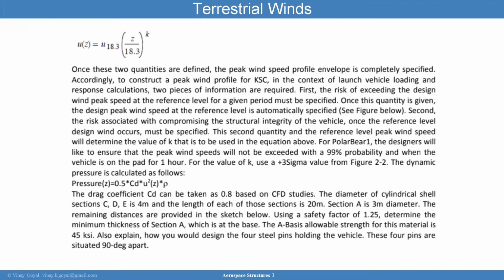Accordingly, you want to construct the peak wind profile for KSC in the context of the launch vehicle loading and response calculations. And you do need two pieces of information that are quite important. First, you want to know the risk of exceeding the design wind peak speed at that reference level for a period of time. So the longer you're on the launch pad, the more likely you are to exceed the design wind peak speed at that reference level.